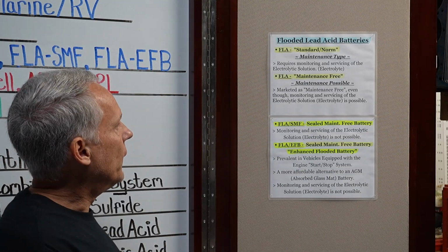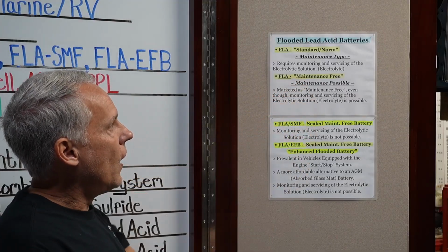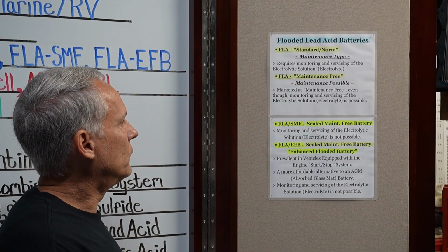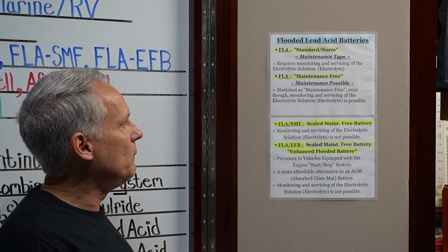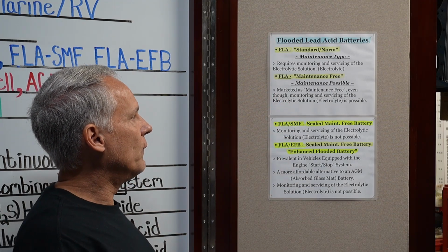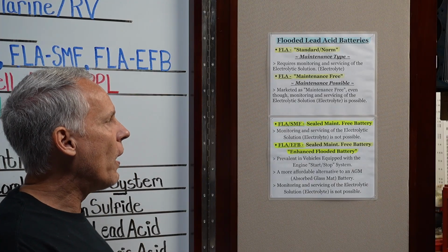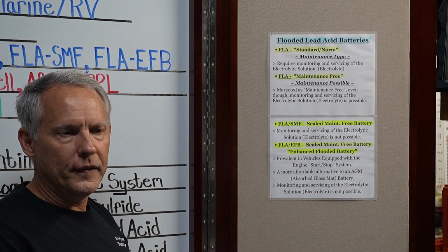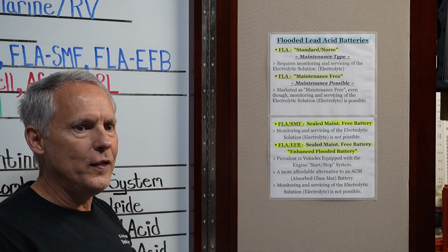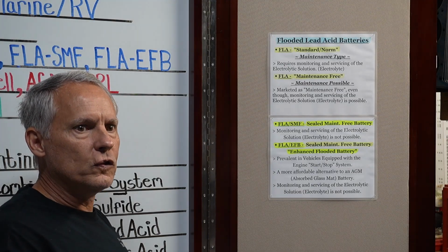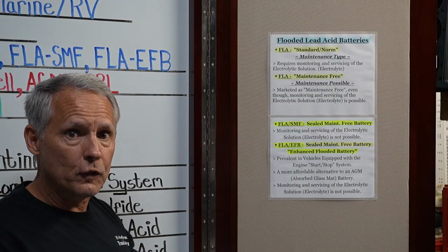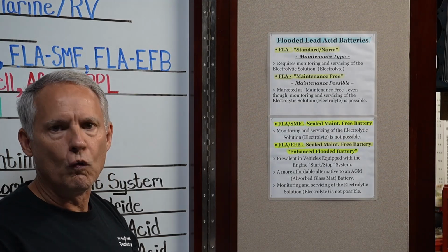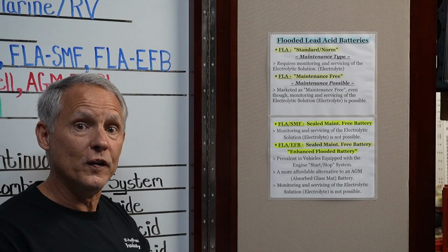Then you get an FLA maintenance free. It's advertised as maintenance free. I call it maintenance possible. What that means to me is that it's marketed as maintenance free, even though monitoring and servicing of the electrolytic solution or electrolyte is possible. And in my mind, not only possible, but highly recommended. If it is an open vent system and you can monitor and service the electrolyte and test the electrolyte, then you should be doing that. If you're not doing that, then, well, you got the wrong type of battery. Maybe you need to get into something that truly is maintenance free.